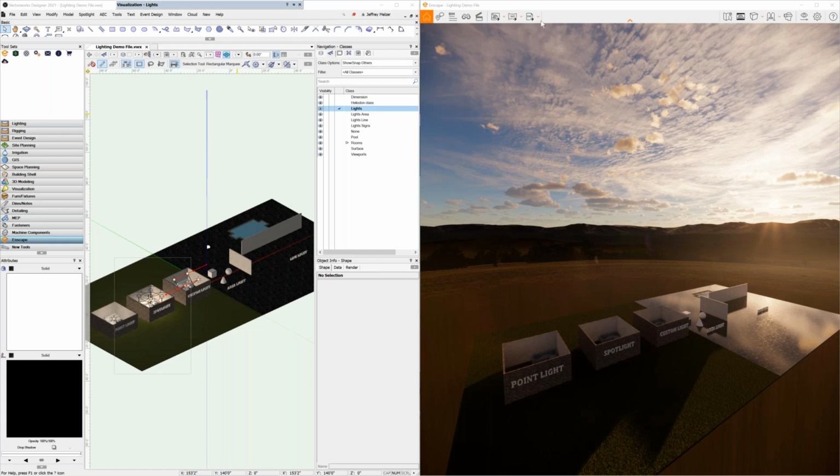After that, we have our executable and standalone options. Now, with those, you can actually build an external file. So with the executable file that you can send to your client, you can actually hand them that file. It'll open, navigation, everything of Enscape works identical. If you don't want to do it that way, you can also export as a web standalone file. Web standalone file is a great thing also. However, you do have to make sure that if you're sending it to a client, the computer still needs to have a little bit of resources behind it, because these are using WebGL and things of that nature, which do take up some power.